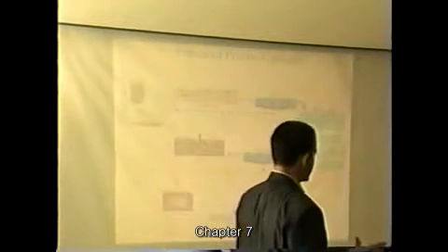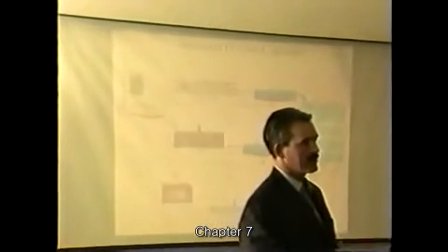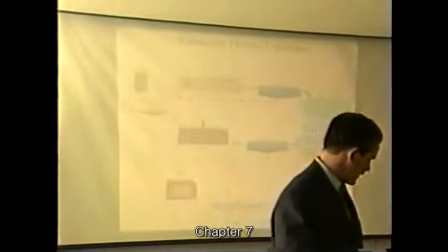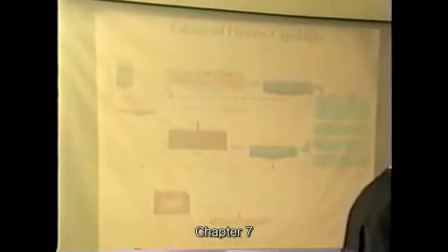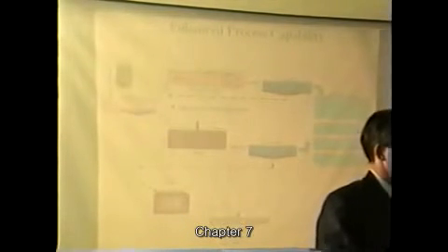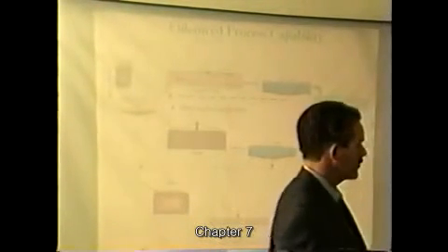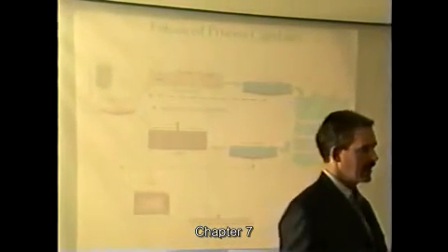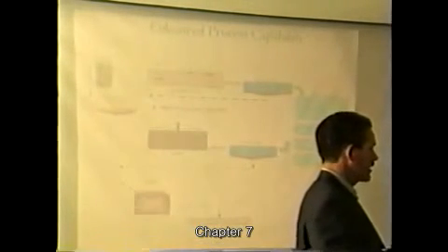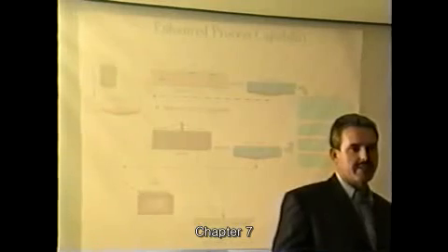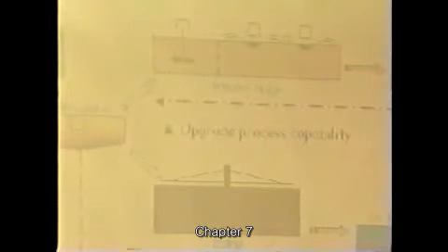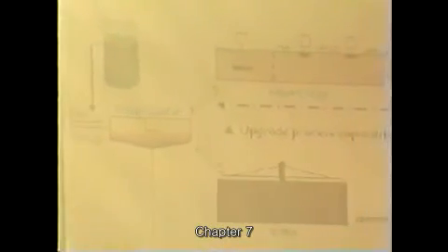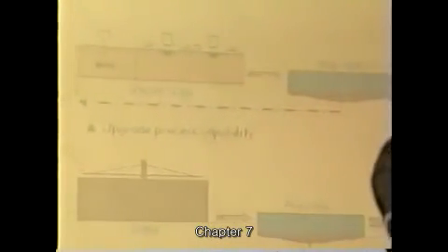If we're looking at what can we do, what does Archaea do for your sewage treatment works? You upgrade your process capability. One of the problems is you have to look at the alternatives. How do you upgrade your process capability? Normally, if your flow has increased or your organic loading has increased, consultants will tell you you have to double your process capability. You have to build more concrete. You will have to put in more aeration, more sludge handling facilities. We say no, it's not necessary.